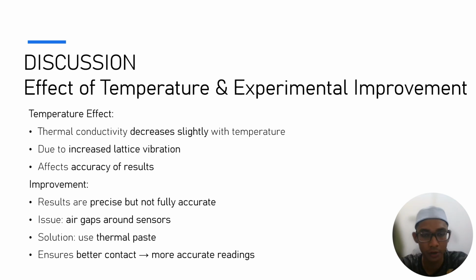Discussion on the effect of temperature and experimental improvement. The thermal conductivity is affected by temperature. For metals, as the temperature increases, the conductivity slightly decreases due to the increased lattice vibration. This will interfere with heat transfer and also affect the readings.